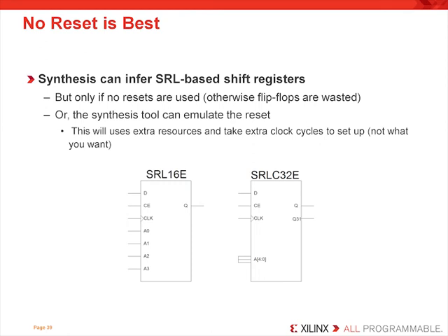Now, emulating the reset means that they add more logic and the design becomes even slower than it should be in some timing critical cases. You should also note that the shift register LUT can easily be inferred when you build synchronous FIFOs, non-binary counters, terminal count logic, pattern generators, and reconfigurable lookup tables. So it's possible that you could infer more SRLs when you code without a global reset, and that of course will reduce your overall size of your design since you'll be saving registers.